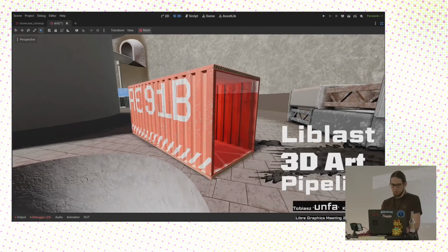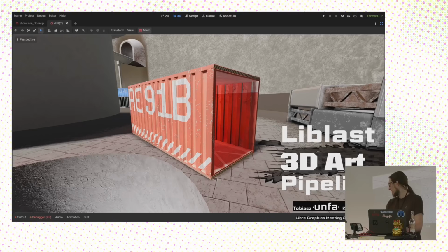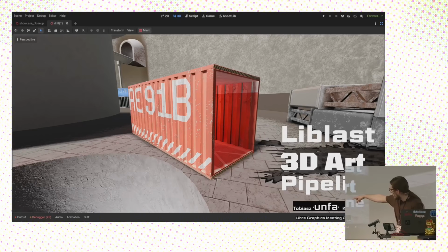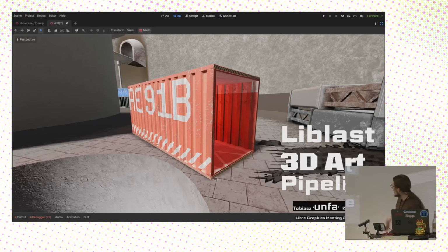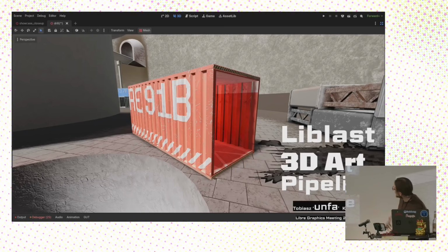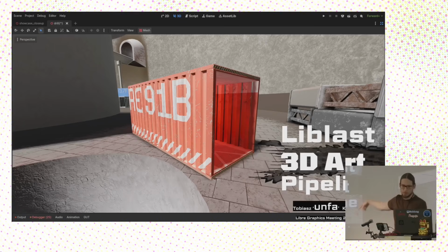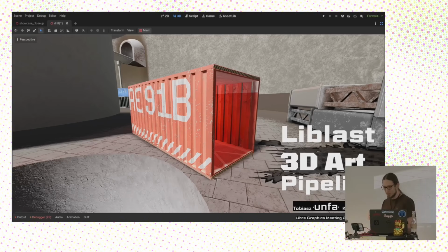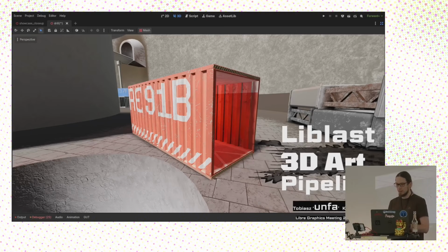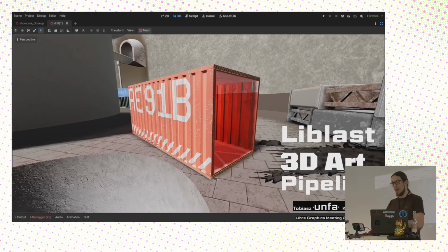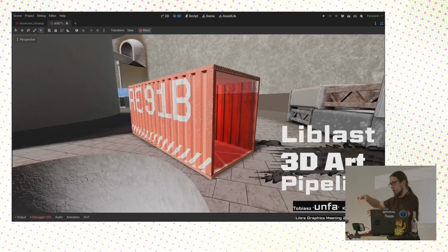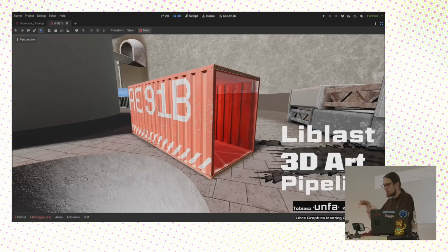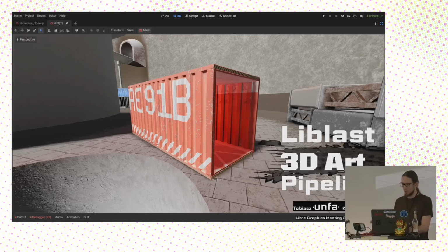This is another view with a bit more environment textures. We have some tiles, and you can see that there's some grunge and stuff in the cracks. There are walls. You can also see that it's hard to spot any tiling on the wall. That's because there are multiple textures. There's a world space noise texture, which is used to break up repetition. It also helps blend assets together, because if you put a bunch of rocks, the world space noise is going to create patches of dirt that are spanning multiple rocks, for example.